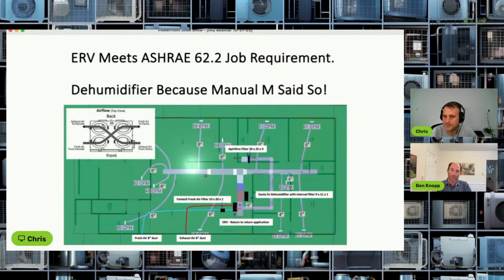The other thing is, it makes a big difference on indoor air quality. MERV 13 is where you start grabbing PM 2.5 in meaningful amounts. And PM 2.5 is the most harmful air pollutant to human health. It's fine particles that go deep in the lungs. Some of them are so fine they just pass straight into the bloodstream, with no defenses that our body can mount against them. They just go right in. So with MERV 13 you start getting like 80% of those out of the air in the first pass. Things like viruses, smoke particles, things like that.